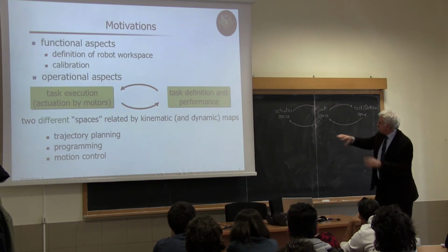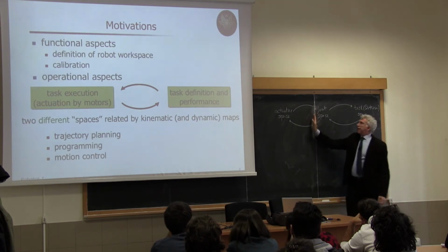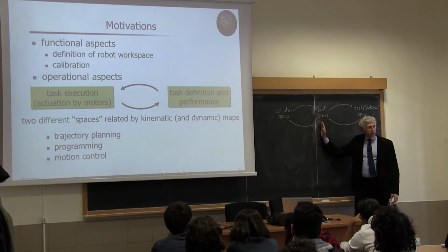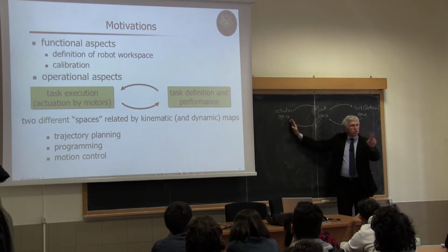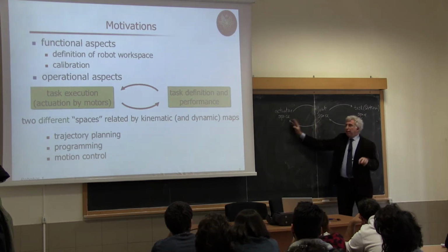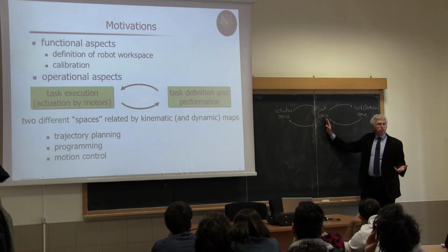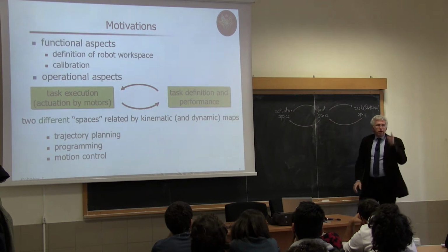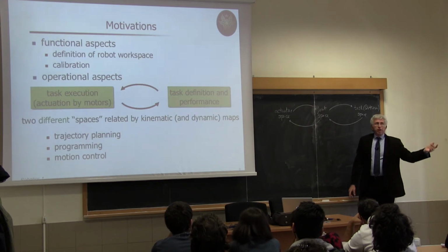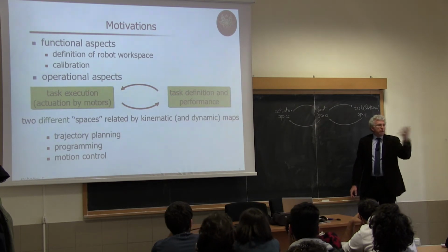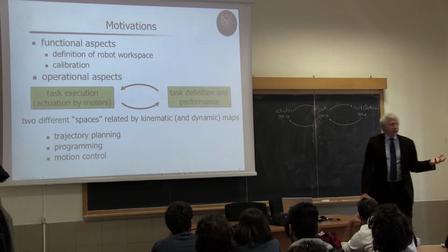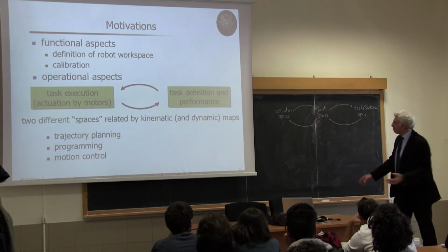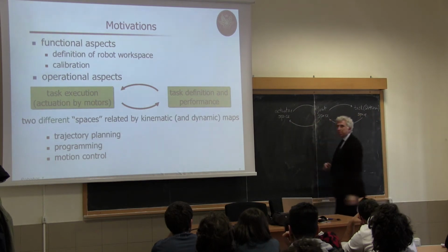So you have some mixing of things, and then it's worth distinguishing between the actuator space, so the rotation of the single motors on the motor axis, and the rotation of the two joints which are connected through a complex transmission to this. But if you assume that you have one motor per joint placed on the joint axis or somewhere else, but through transmission you have at the end only a scaling factor, then you can merge actuator space and joint space.